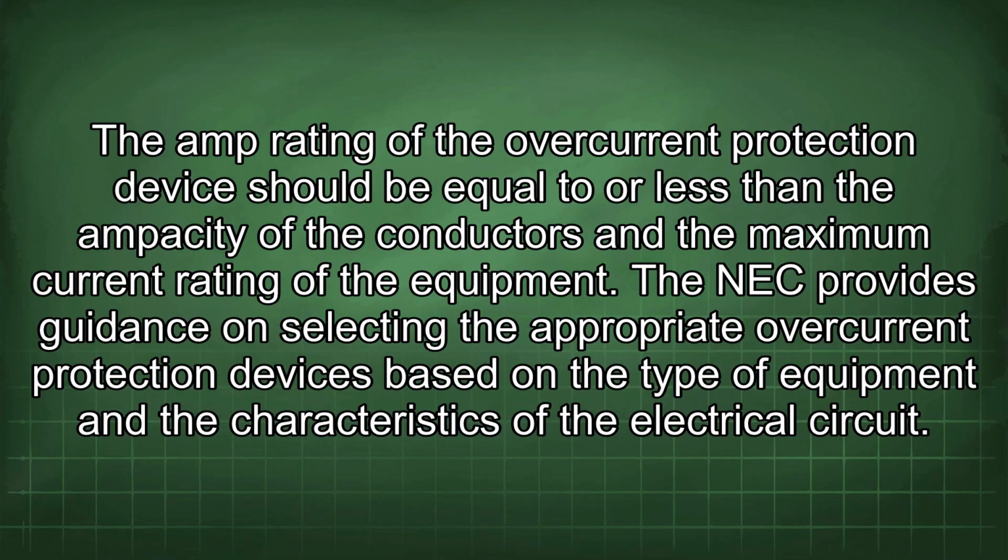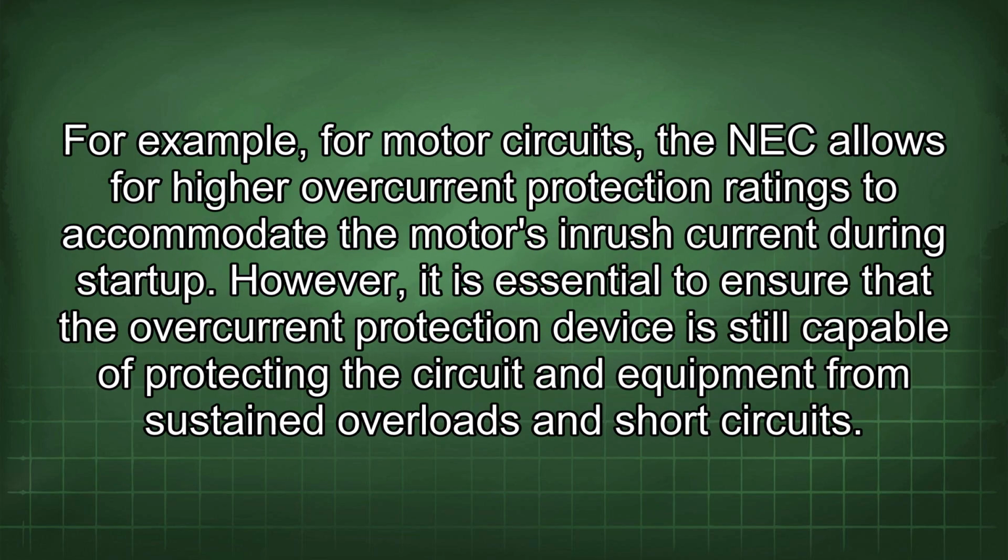The NEC provides guidance on selecting the appropriate overcurrent protection devices based on the type of equipment and the characteristics of the electrical circuit. For example, for motor circuits, the NEC allows for higher overcurrent protection ratings to accommodate the motor's inrush current during startup. However, it is essential to ensure that the overcurrent protection device is still capable of protecting the circuit and equipment from sustained overloads and short circuits.